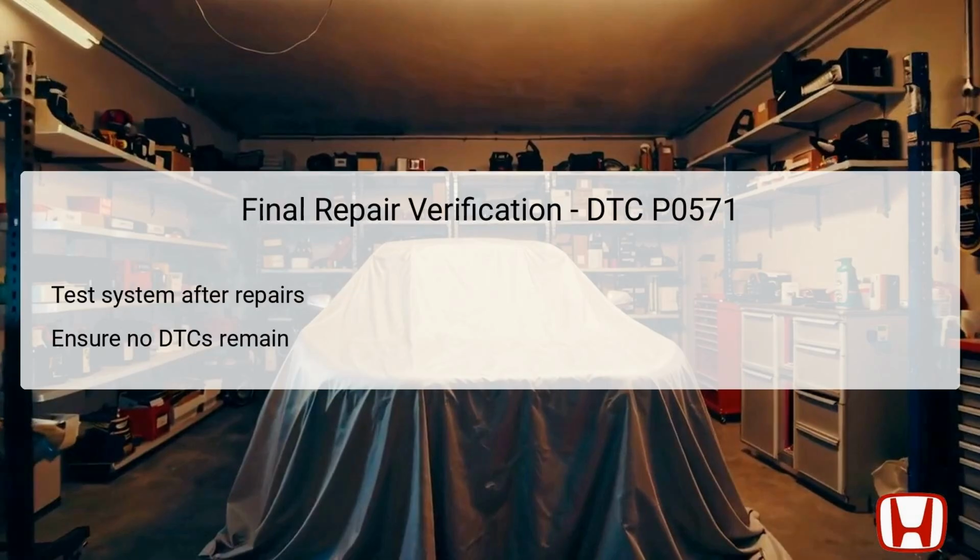After repairs have been made for DTC P0571, a final verification of the system is essential. This involves testing to ensure that the brake light system is operational and that no diagnostic trouble codes, DTCs, remain present. Utilizing the Honda Diagnostic System, HDS, to recheck for any active or pending codes helps confirm that the issue has been resolved. Completing this verification establishes certainty that all related systems are functioning appropriately and that the vehicle's safety features, including brake lights and cruise control, operate correctly.